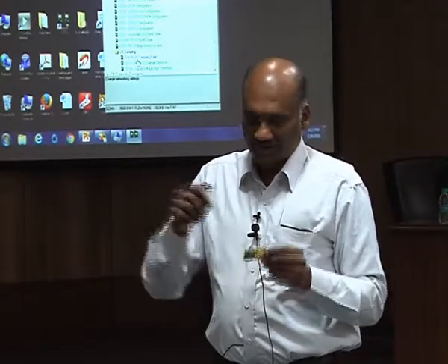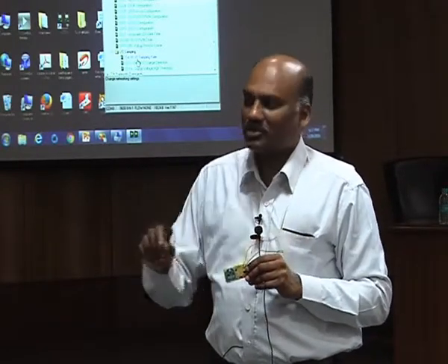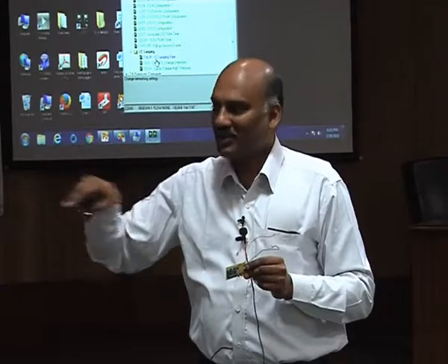Since in this particular ZigBee module the reference voltage is also 3.3 and our VCC is also 3.3, what we have done is connect whatever voltage goes to the VCC so that it also goes to the reference voltage pins. There are two pins meant for that in this design. Pin number 1 and pins 14 and 16 are equivalent: whatever voltage comes to pin number 1 also goes to pin number 14 and pin number 16. The same 3.3 volts goes there. Pin number 10 is ground only.